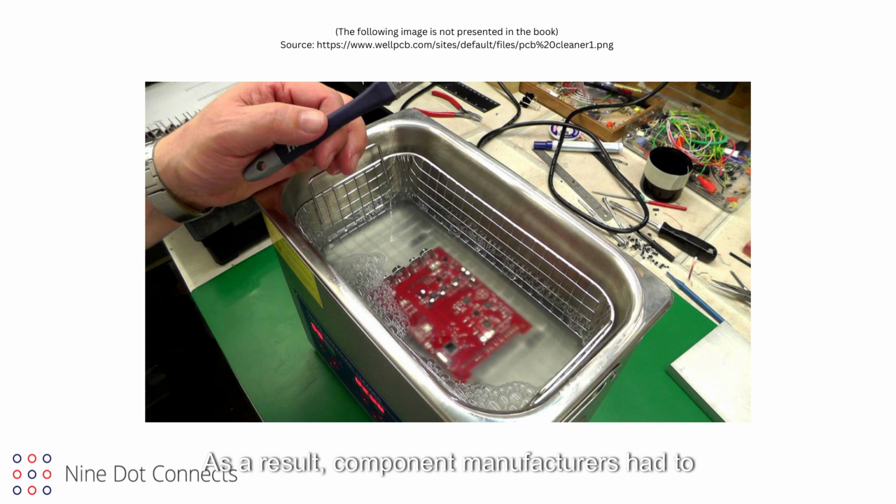As a result, component manufacturers had to modify equipment to handle the lead-free solder formulas. The United States has not adopted RoHS as law, except for the state of California. However, China, which is a worldwide producer of electronic components, adopted RoHS. Given the global nature of the electronics market, all electronics companies in the US have adopted RoHS to sell their products globally. To meet these challenges, newer chemicals and techniques are always emerging, but the fact remains, the PCB must be cleaned, and the parameters defining the cleaning process must be thoroughly understood by the assembly house.